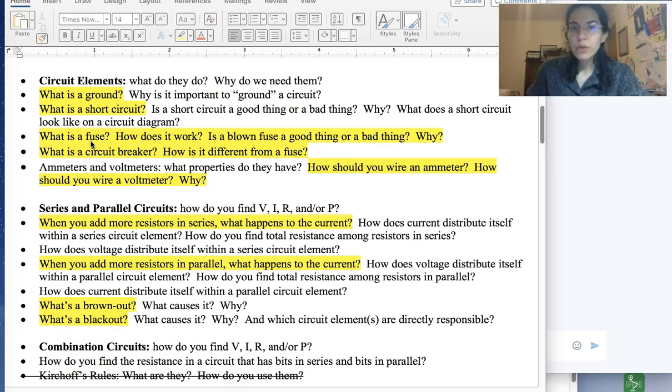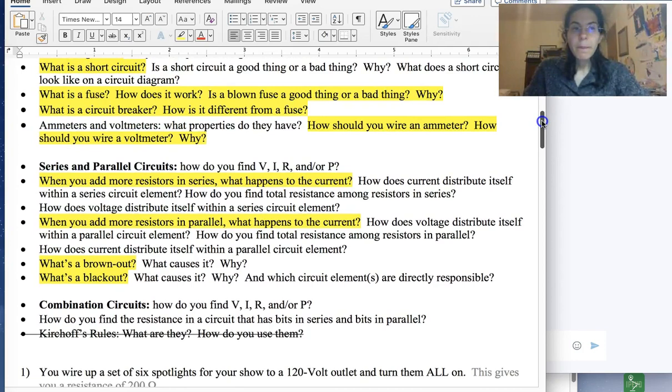Know how a fuse works and how it sacrifices itself to prevent the overheating and electrical fires you saw with circuit breakers. Know that you have to fix the problem before you replace the fuse, and you do have to replace a fuse because a blown fuse is permanent. If you're working with a large appliance or a building, you know the symbol and know why you would be using a circuit breaker rather than a fuse, which can be reset.